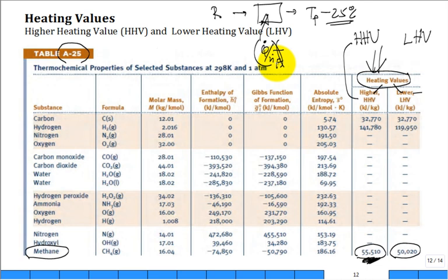So basically the higher heating value is where all of the products go out at 25 degrees C. You know what? For lower heating value, all the products go out at 25 degrees C as well. And then why do they have two values? It's your maximum heating value. And once I say it, it'll be obvious, but what is coming out in our products? Carbon dioxide, water, nitrogen.